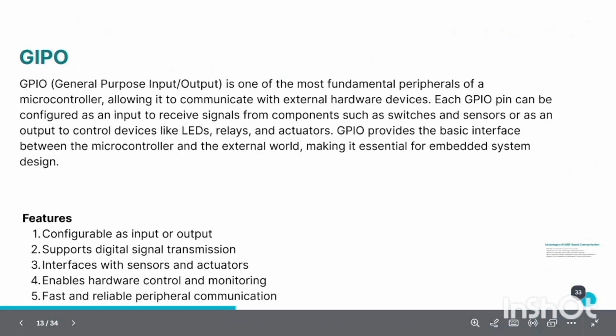GPIO, General Purpose Input Output. GPIO pins form the fundamental digital link between our code and the outside world. Each pin can be dynamically mapped as an input to catch sensor transitions or as an output to generate trigger signals, enabling fast, low overhead digital device control.